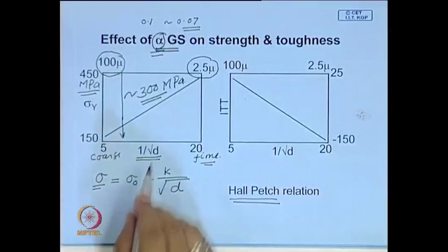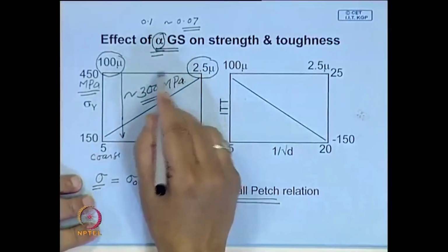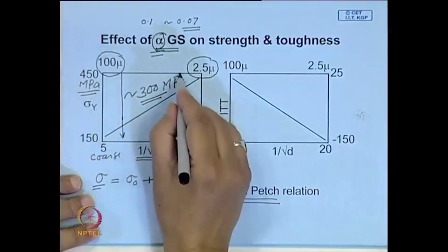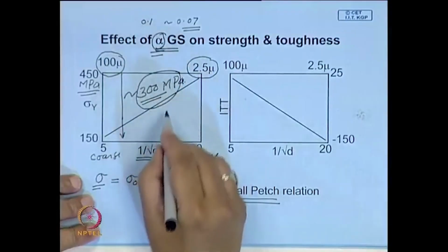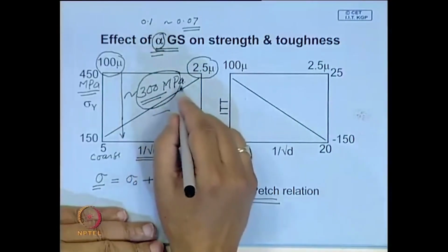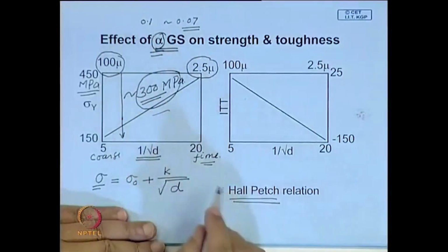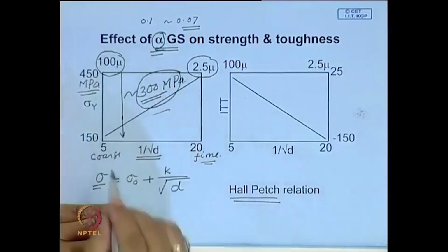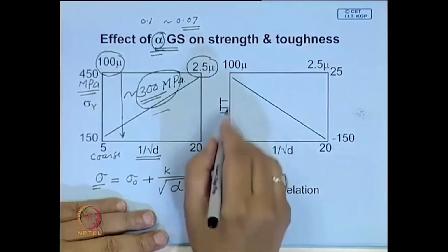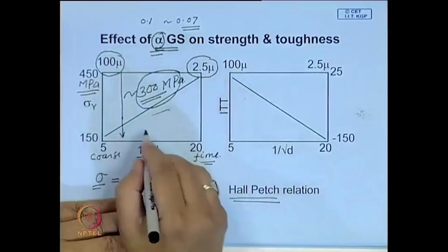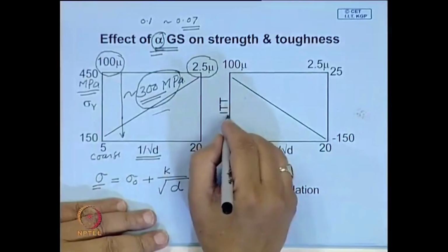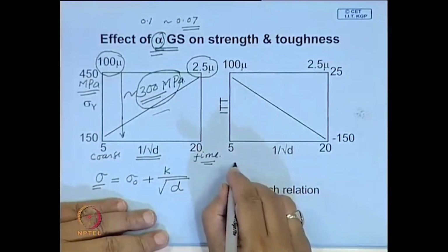And we will see, if you check, solid solution strengthening can never really approach such a high magnitude of strengthening. Most solid solution strengthening may be of the order of 50, 60 MPa, depending on the alloy element. And since the grains become finer, it will be more difficult for the crack to propagate. So, therefore, we expect that this ferritic steel will have much higher toughness, and one measure of this toughness is transition temperature.